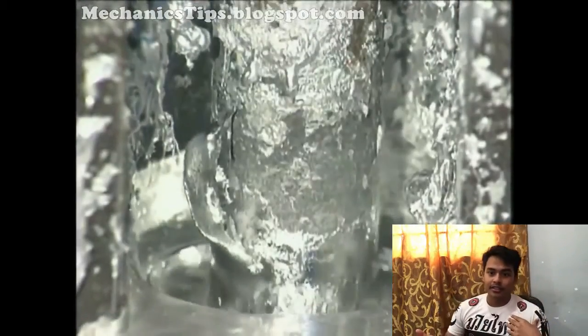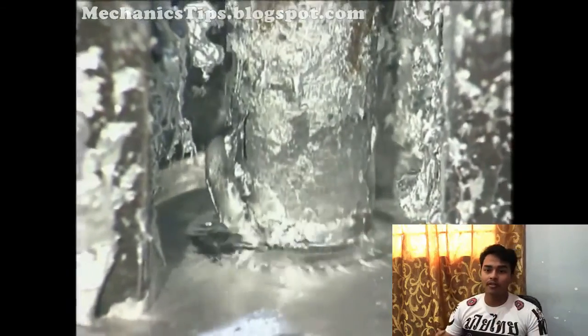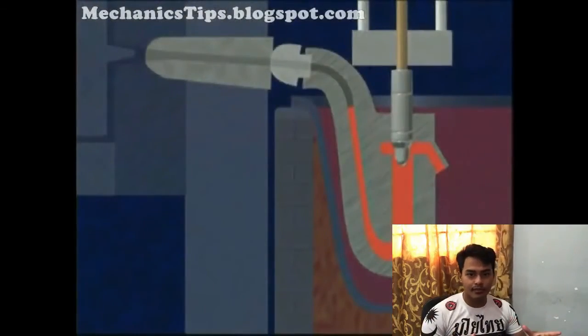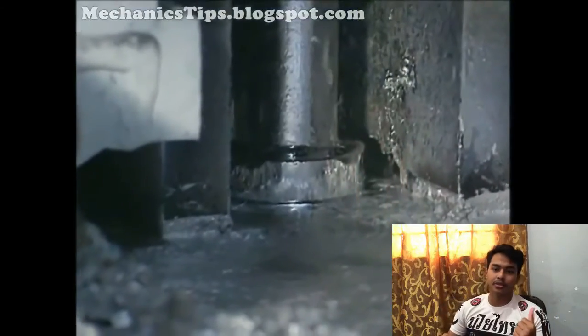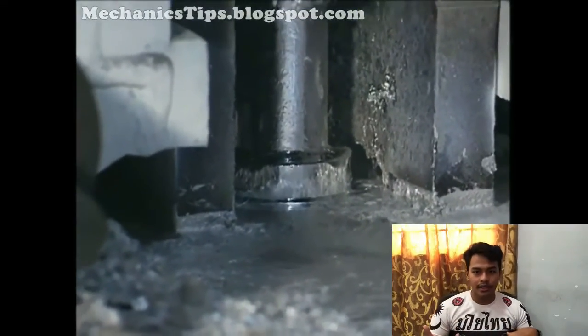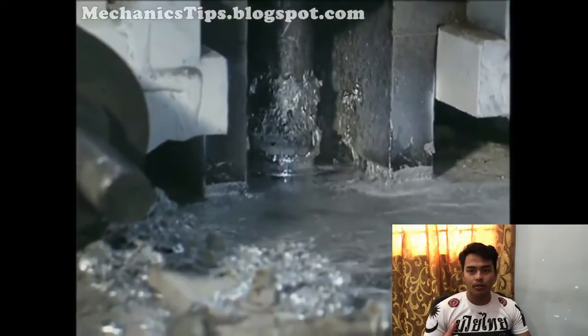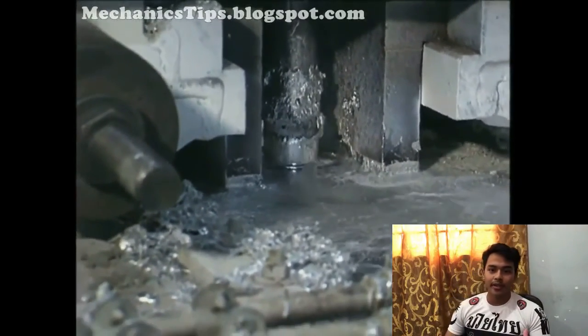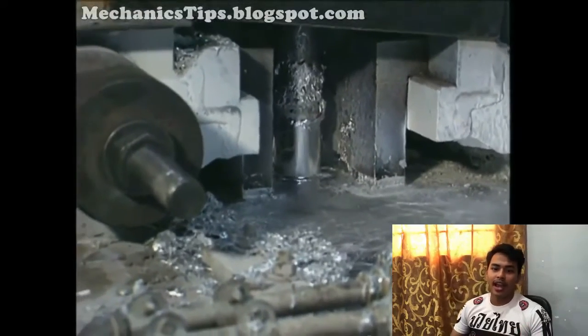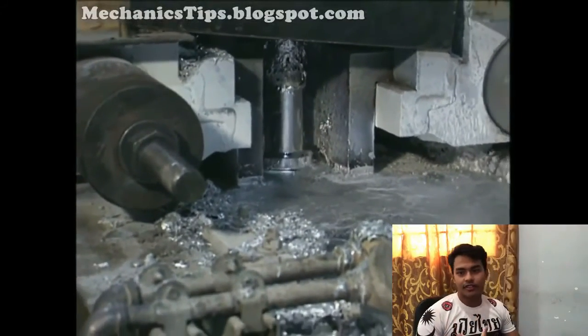In the standard die casting process, the final casting will have a small amount of porosity. This prevents any heat treating or welding because the heat causes the gas in the pores to expand, which causes micro crack inside the part and exfoliation of the surface.